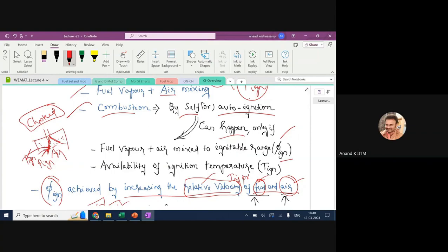So that's why it's very important to create an appreciable air motion, so that air goes in continuously and fills this space, and the products of combustion leave this space. Creating air motion inside the cylinder plays an important role. This is one of the reasons why CI engine combustion is also referred to as a mixing controlled combustion event or mixing limited combustion event.